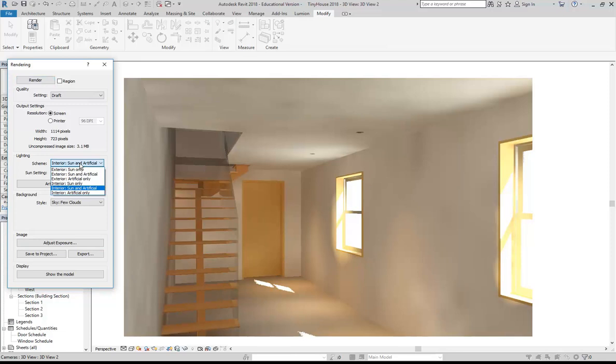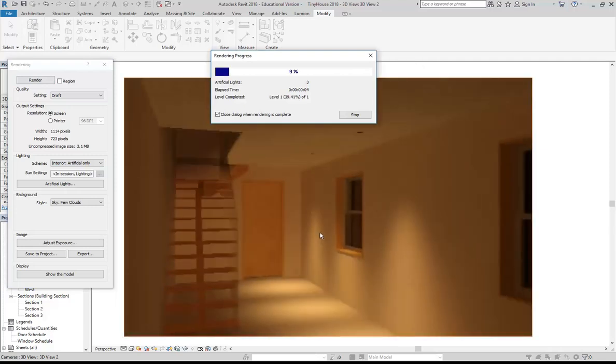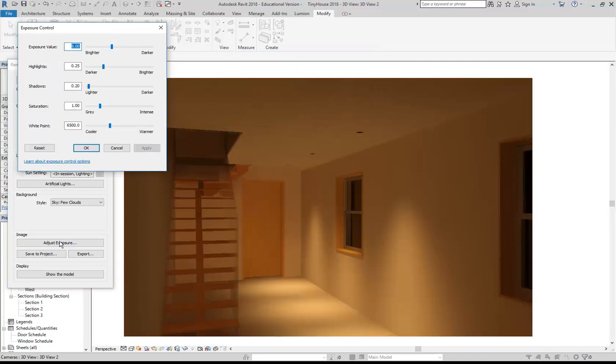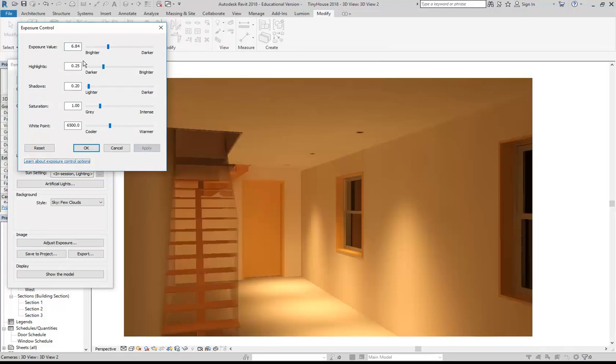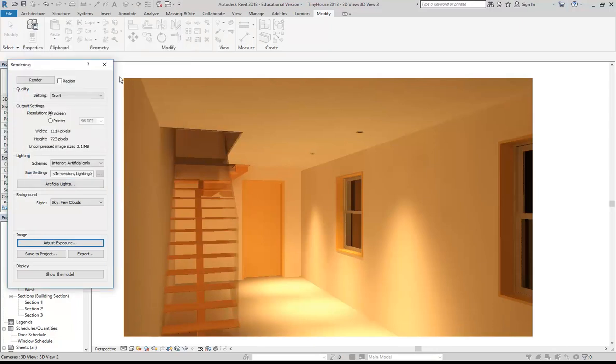Yeah, look, it's okay, but... Yeah. It is brighter, but again, it's just like in photography. When you take a photo in a darker environment, you simply need to adjust the aperture accordingly. In other words, let more light in. And this is what your eyes do naturally, when you go from a dark to a light or a light to a dark environment, your pupils adjust to let in the right amount of light. Okay, so that's again using the exposure there. As I add more lights though, I'd need to come back and reduce the exposure.